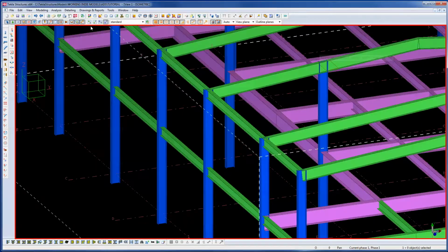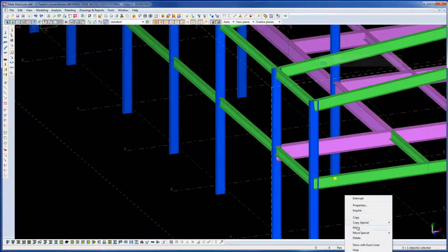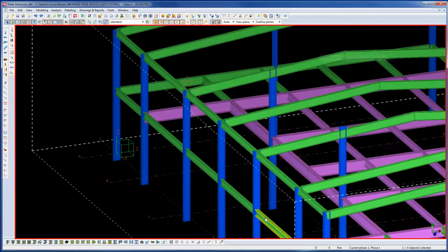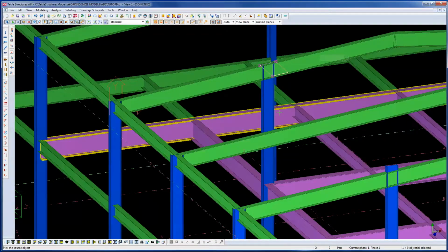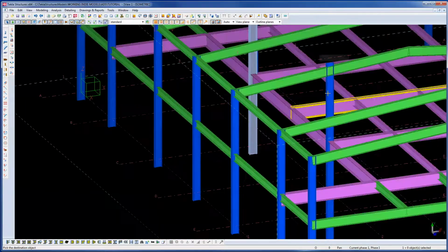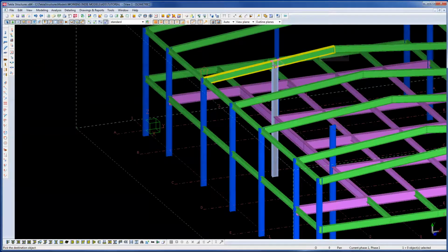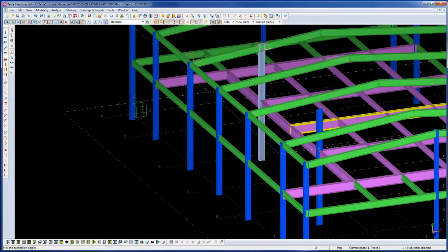However, just to demonstrate, if I undo that, I'll extend, Alt, move, drag it down. I've got my O snap on, drag it down a meter, and then if I copy that object to that column, you'll see it's cut it, because it's put the cut the same distance from the end of this column as it is from the end of that column.